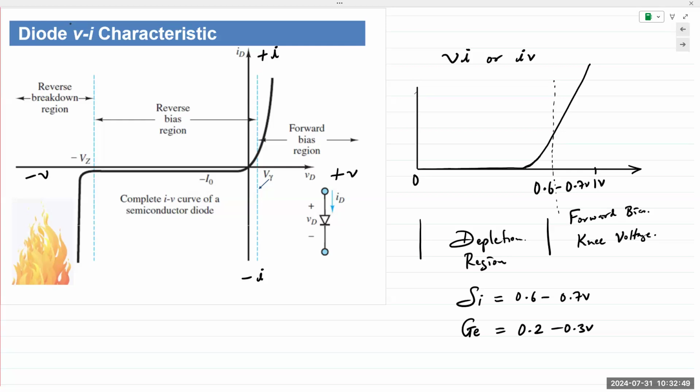So there is electric current flowing, but whenever we say electric current is flowing, it means that there are charge carriers actually flowing through the junction. They transfer the energy across the junction and into the terminals, but they would not specifically leave the terminal as such. Physically leaving the terminal? Physically, no. Energy is being transferred. The energy would go, the charge would go, but not the actual electrons or holes themselves.